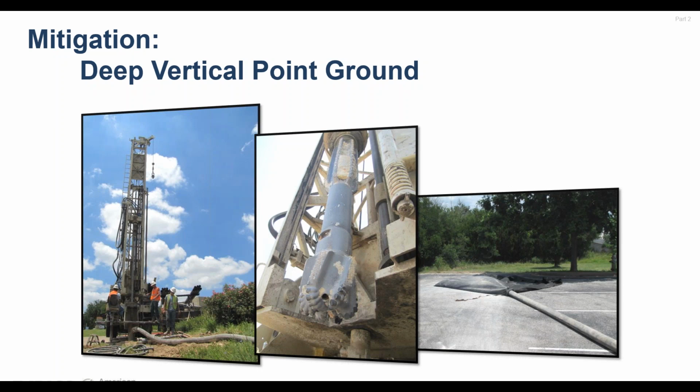In this particular example, what we're showing you on the far left is the drilling rig apparatus. Rather substantial drilling bit was required in this particular location because of the rock formations that we encountered. And it happened to be done in an urban environment. So while we were drilling with air equipment, we needed to contain the dust. So you see a giant dust bag on the discharge side of the rig.